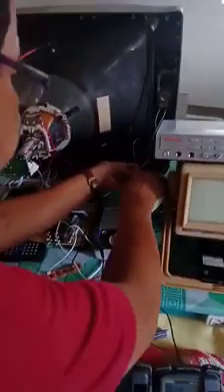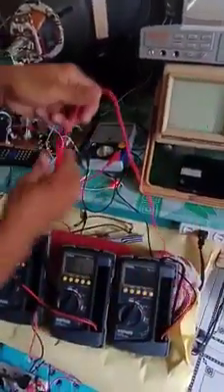Okay, you may connect it here, or you can connect this one here, or here, or here. But it is appropriate here because it is away from the circuit, but it is still negative side. Connect this negative of the DC voltmeter to the negative side of the circuit, whereas the positive side will be injected to the electrodes of the transistors or terminals of the IC.